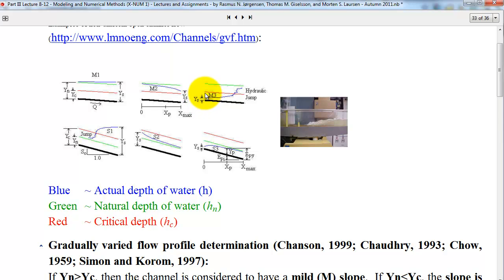If you take an example, for example this one, if you have a dam, like here, let's put a block here. That means that water is coming out here from a very low height and will come with a high speed. That means there's a lot of energy in the water, and this shear along the surfaces will kind of break the water, and suddenly you will end up with turbulence, and that will extract energy out of the system. That's the same as reducing the speed, and the water height will increase and get closer and closer to equilibrium.